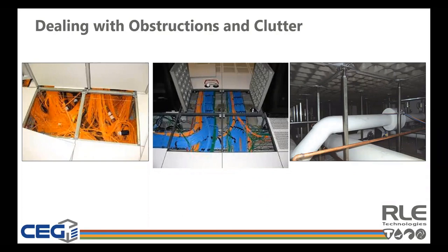The other thing is a lot of people are doing it overhead now. It might be power under the raised floor, data overhead, fiber troughs for fiber, and then a ladder rack for copper. That gets rid of a lot of this, but you'll be shooting yourself in the foot if you just put the floor tile down on top and say, I can't see it, therefore it doesn't exist. Hey, good points, Rob.